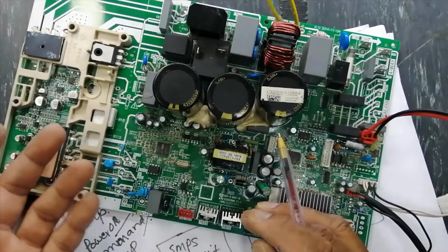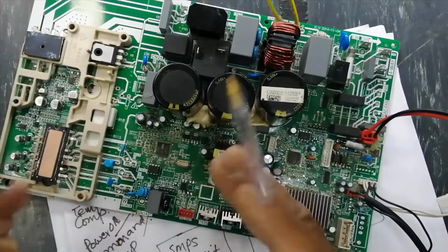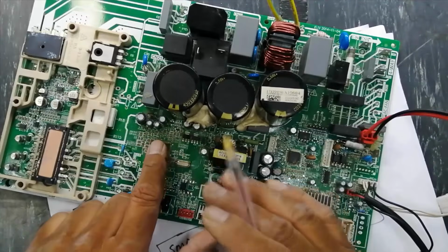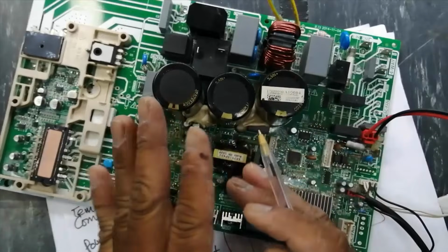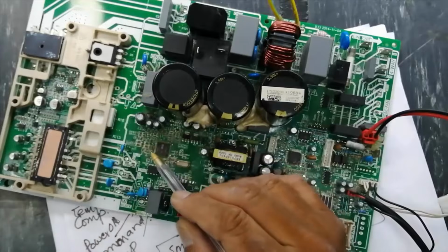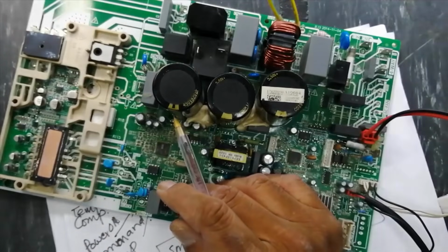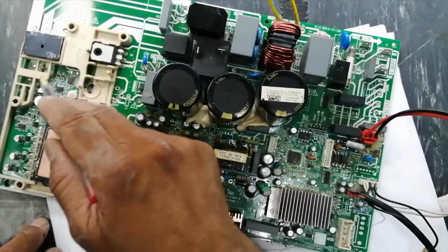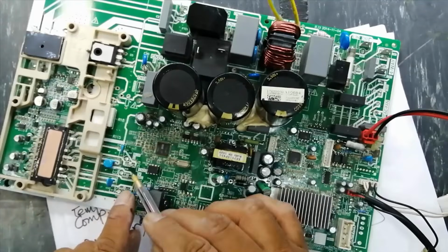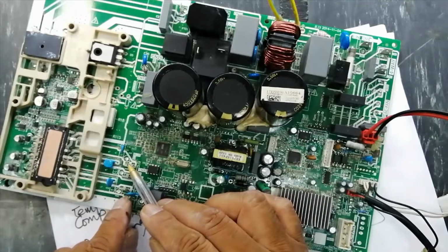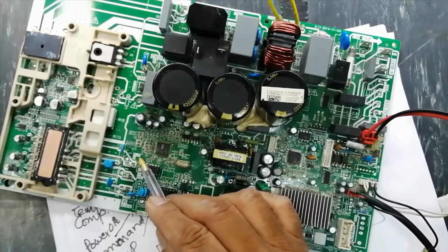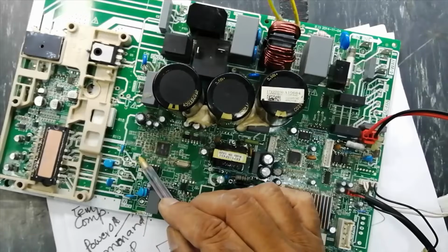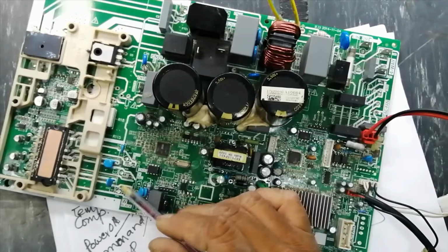Slow running, fast running. It will make a sequence between the phases, and we will receive its command signals, every phase, high and low drive. We have 3 phases, so it will generate 6 lines, and it will ensure the phase combination is in exact sequence. So everything will flow in this way, and our compressor is connected between these 3 terminals, called UVW. The blue wire is here, the red wire is here, and the black wire is here, W.